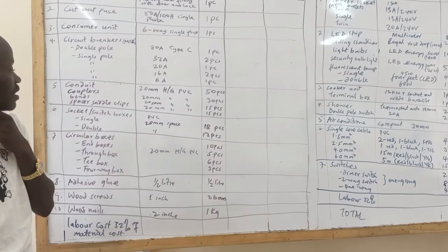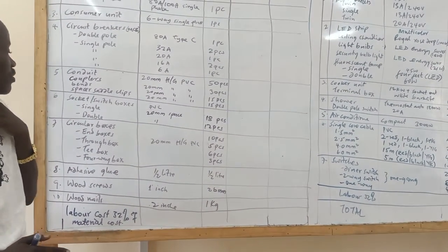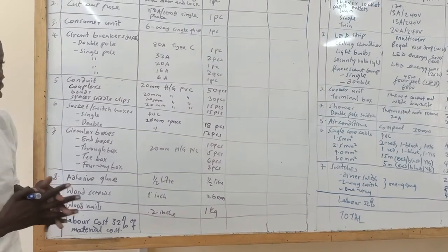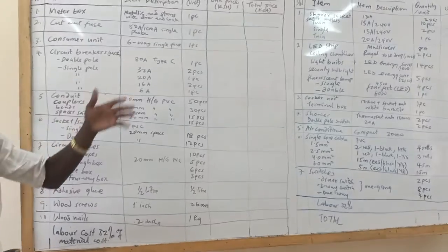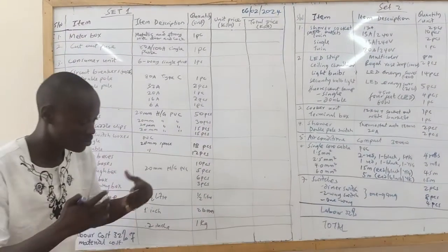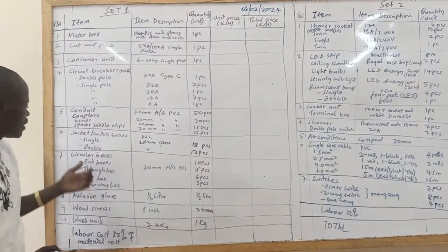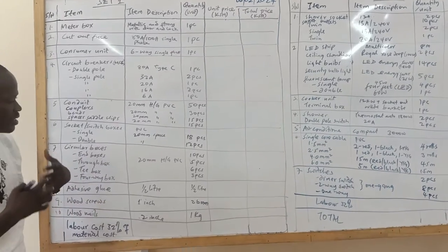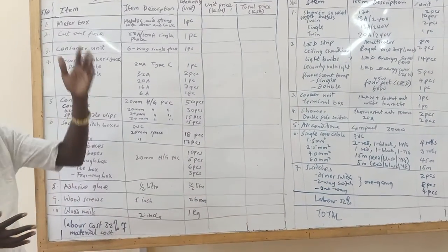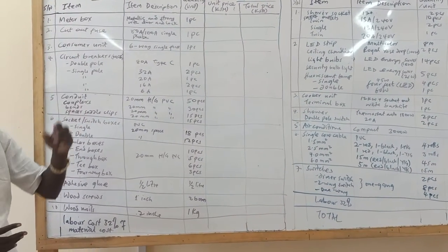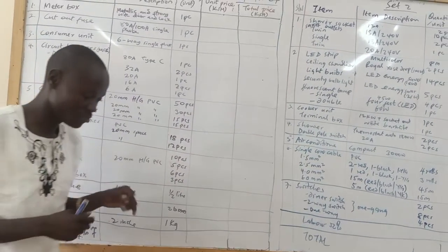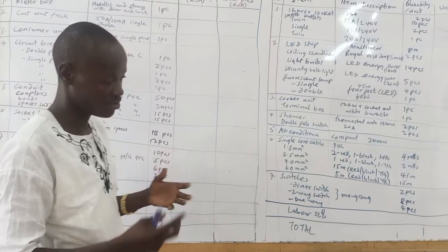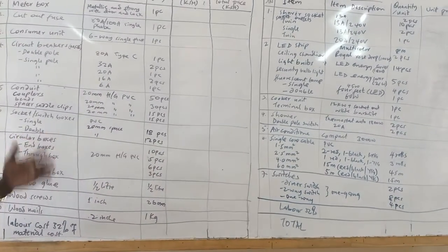Then the boxes, the socket boxes, this one for the spacing of the switches, where the switches will be, where the sockets will be, where the cooker will be, where the lamp board switch will be. And then circular boxes for all where the lamps will be. So every lamp position, say the ceiling rose, and some just below it, I will have a circular box. That's where the termination will take place, or the drawing cables will pass by, then the termination will proceed.